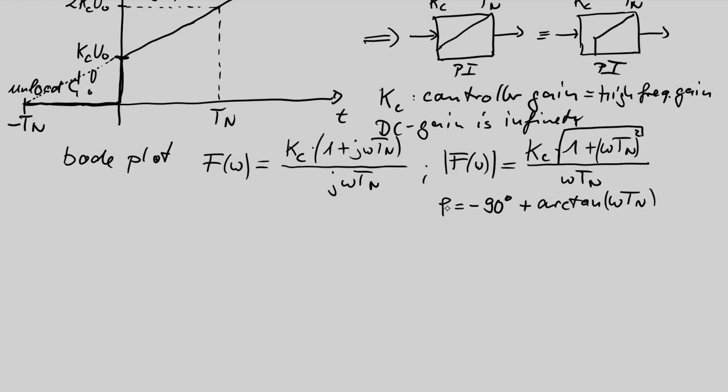But now a Bode plot. If we have done this several times, you see the result can be more and more quickly written or sketched. We use again the asymptotical construction.